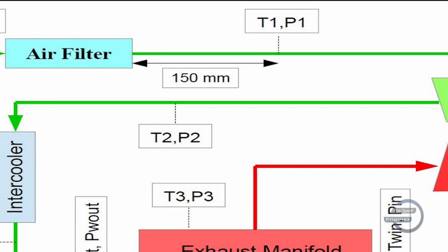The reason for capturing the temperature after the filter is to analyze the effect of the engine compartment heat on the fresh air, because the air filter and compressor inlet are connected by an inlet hose, which is made of either metal or rubber. Hence, the effect of surrounding heat can impact the fresh air temperature. So, that is why capturing T1 is very important.